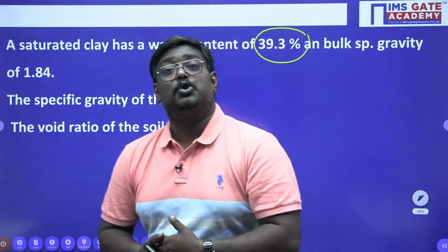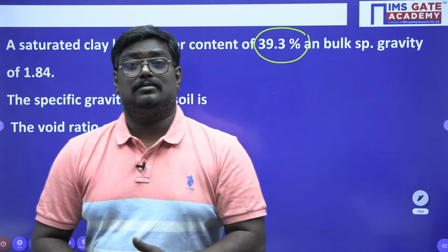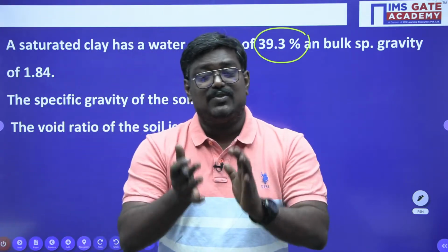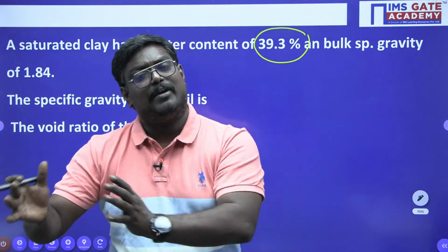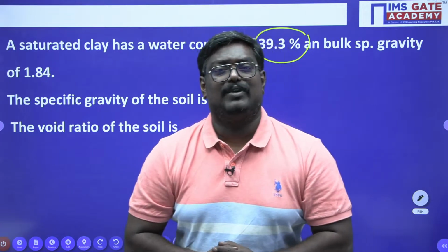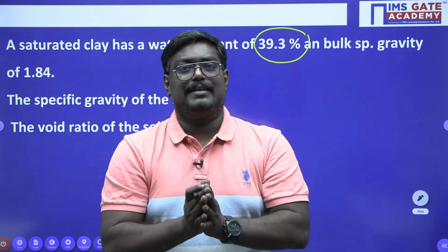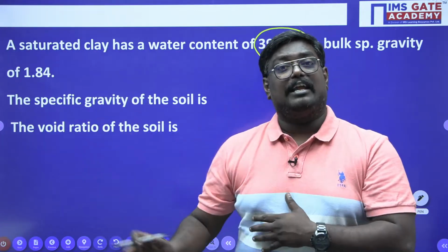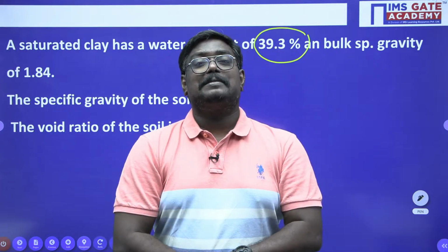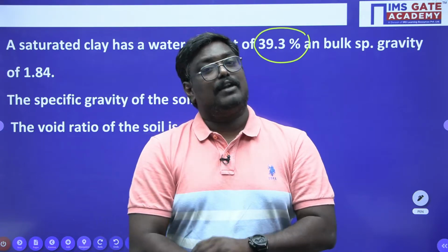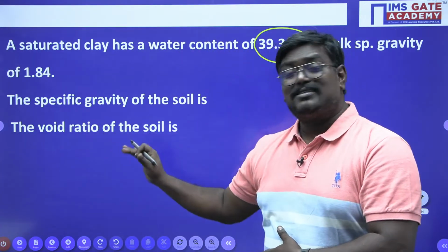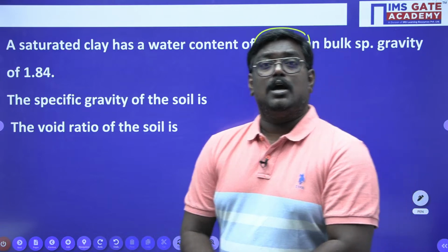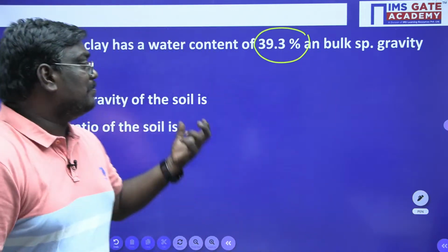See, this question you can ask me, my dear students: whether it is mass specific gravity or true specific gravity. Remember, whenever you are solving, the term specific gravity by default is nothing but the true specific gravity of the soil. And he has asked what is the void ratio of the soil. So let us solve this problem, my dear students.